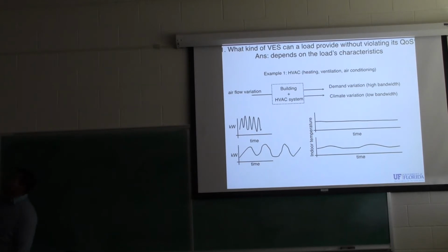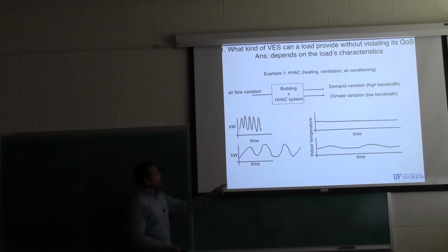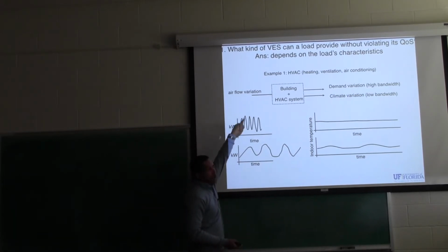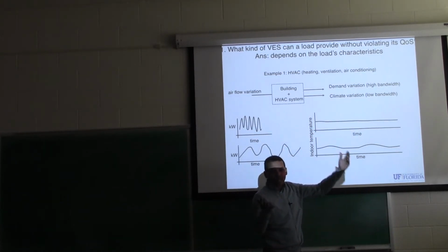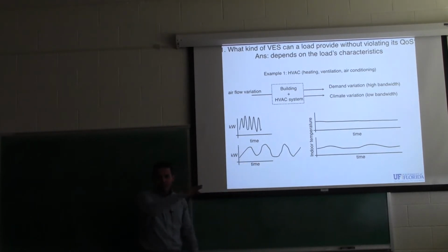Now, if I take that airflow, if I increase it by 10% for 10 minutes, and then decrease it again by 10% for the next 10 minutes, you and I would not feel any difference, right? But power consumption is going to go up and down every 10 minutes now, if I keep doing that, right? So that's like a battery charging and discharging every 10 minutes, if you take out the baseline. And the effect on temperature is nothing, because the building is going to act like a low-pass filter to this high-frequency input signal. And that happens because the structure has large thermal inertia, right? That's why we don't feel any difference.